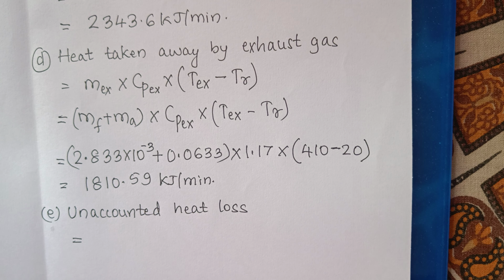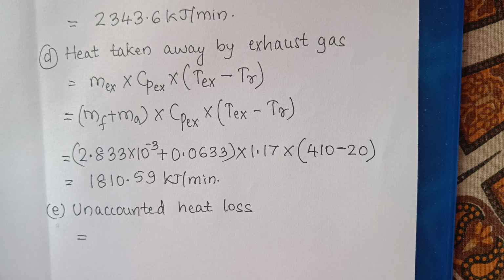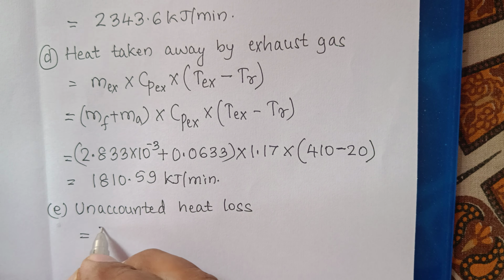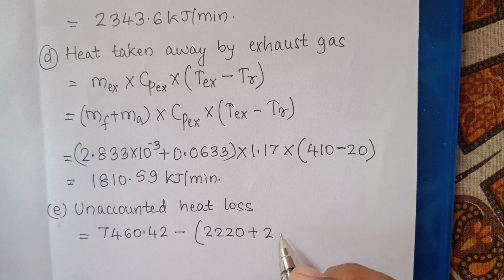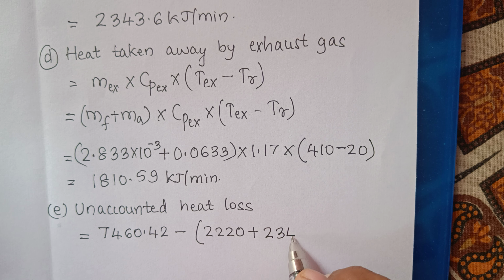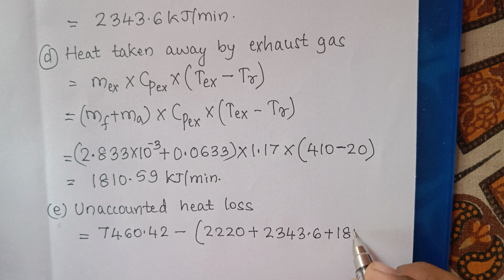So it is nothing but heat supplied, that is 7460.42, minus heat equivalent to BP, that is 2220, plus heat carried away by cooling water, that is 2343.6, plus heat taken away by exhaust gas.